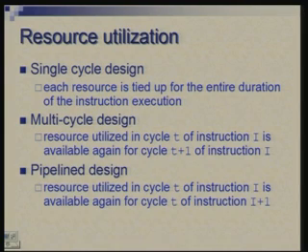In single cycle design, each resource is tied up for the entire duration of the instruction execution, whereas in multi-cycle design, resource utilization is better. A resource which is utilized in cycle T of instruction I is available again for cycle T plus 1 for the same instruction I. So, a given resource can do whatever is required in different cycles for the same instruction.